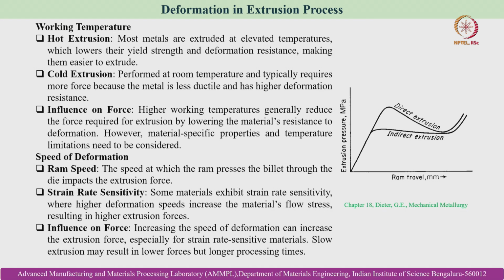So, slow extrusion may result in a lower force requirement, but longer processing times. To decrease the processing time, we increase the speed of extrusion. So, that will significantly cause a requirement of higher extrusion forces.